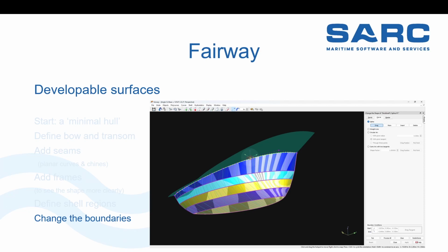Actually, there are some features for that. You can project the curve from a point. So if you find a circular point at the pipe and project it onto the hull and connect the curves that you have, you will have a developable scallop plate. Or there are many ways to go about it. But in general, for shapes here, as long as they are parallel along the rulings, maybe in different places, then you'd have a developable plate within two chines.